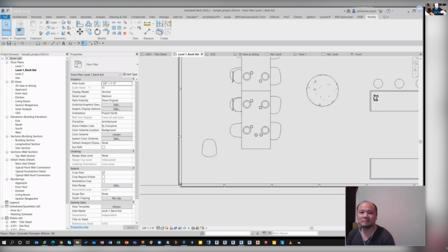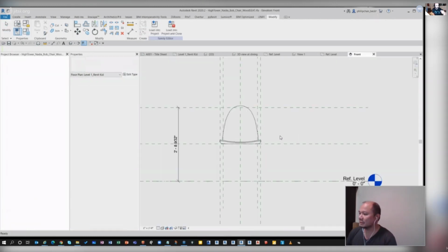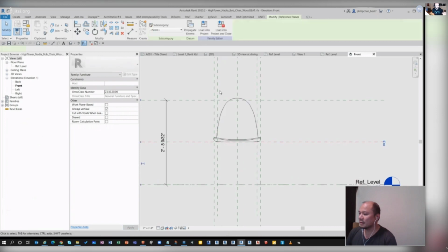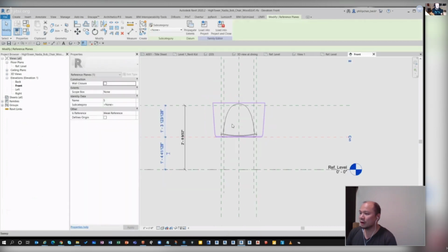That reference plane was sitting somewhere in the leg geometry, and that's why you had that weird thing happen. But that's really cool. I actually never even thought about taking that route of rehosting, because by default, if you go back into that family, what does it default into? Your reference level, or is it just not hosted? No, not hosted. It was not associated. It's not associated. So then it's just going to always be in front, basically, right? If it's not hosted. So based on that idea, I think you might be right.